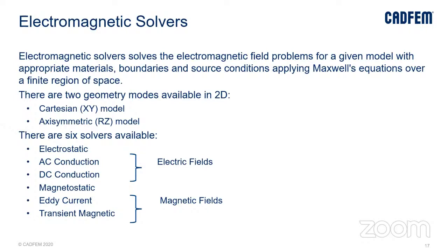To understand all sorts of applications, when you talk about those four basic equations, there are static equations and there are also dynamic equations. To understand those, any solver has to provide these six sets of solvers. Those are static applications, electrostatic and magnetostatic, the steady-state fields, which we can also call eddy current, and AC and DC conduction. When there is AC and DC from the electric point of view, how is it going to behave?